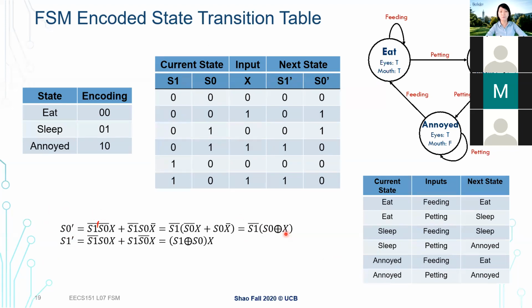We talk about 3 very important components of any finite state machine: the inputs, the outputs, and the states. So here we know how our states transition, how the next state is determined by a combination of the current state and the current input.